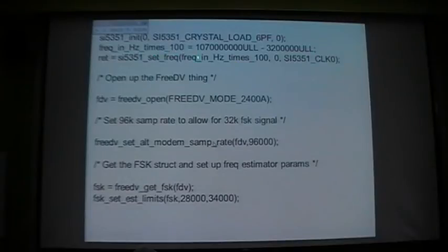And then we tell the local oscillator chip that's the frequency we'd like, and away it goes. So if you had to tune to another frequency, you'd get an input from Hamlib. You'd change that number and you'd change your tuning at the IF point. Although I guess you couldn't change it far on the IF point because your crystal filter wouldn't work, but there'll be another local oscillator that's very similar for the first mixer to tune the VHF.